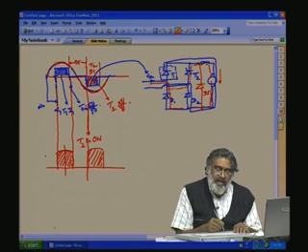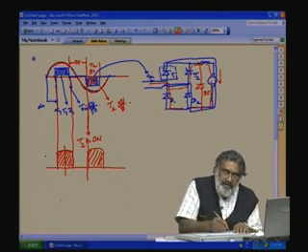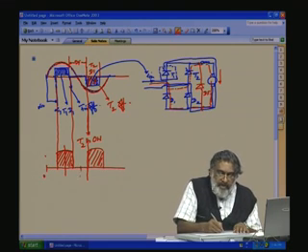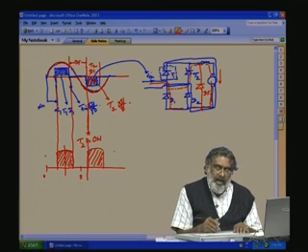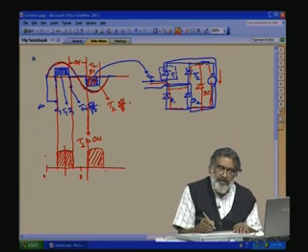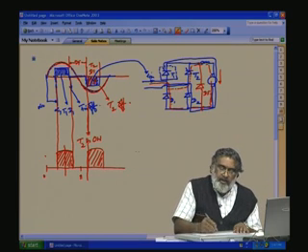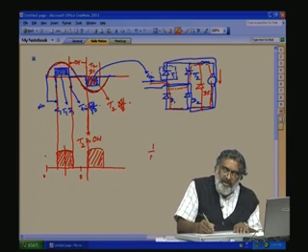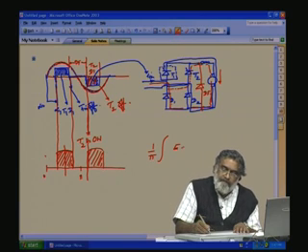Here, what will be the output DC voltage with respect to firing angle? We know this is 0. This center will be pi. So, the output ripple frequency is 2 times the fundamental. So, what will be the output voltage waveform here? The period is equal to pi, 1 by pi times the average value integral, let us take Em, Em sin omega t d omega t.